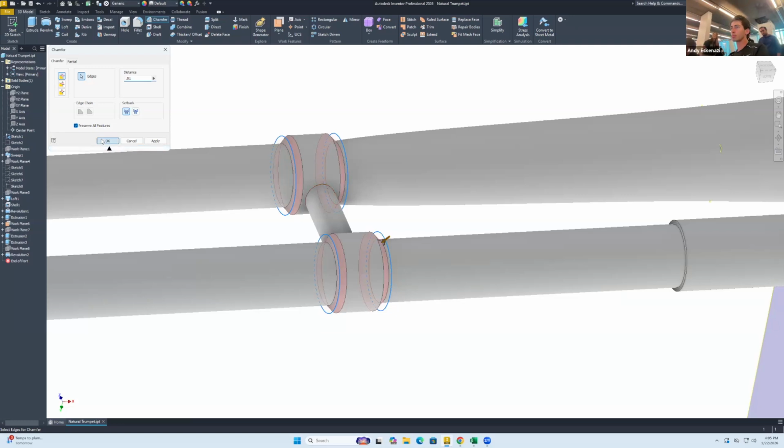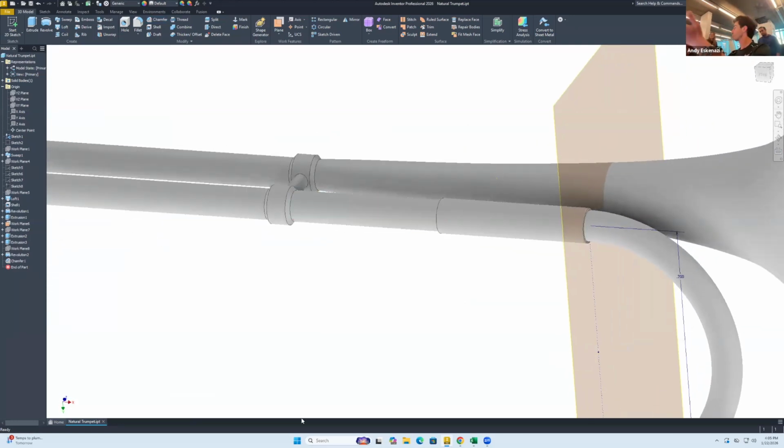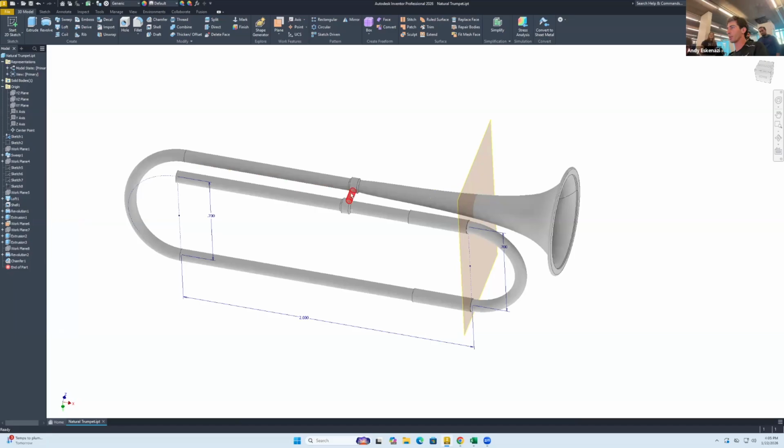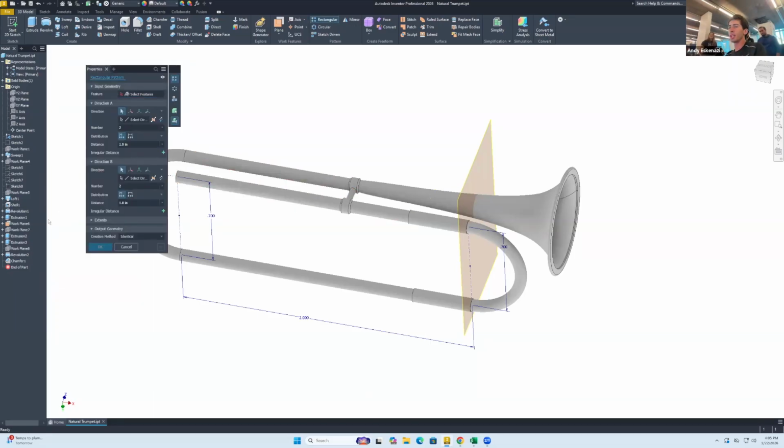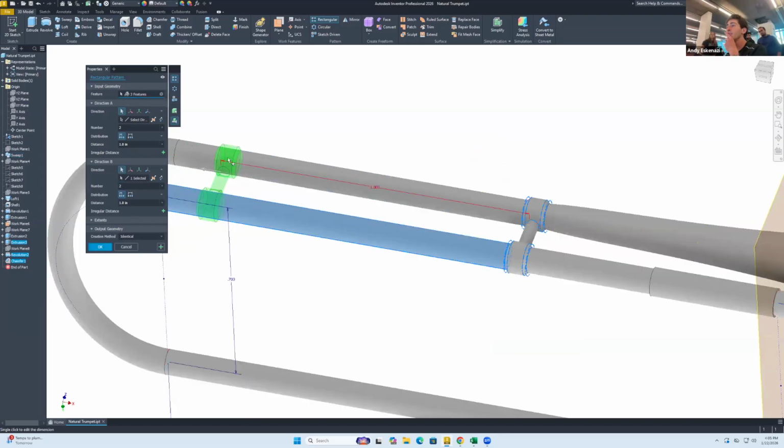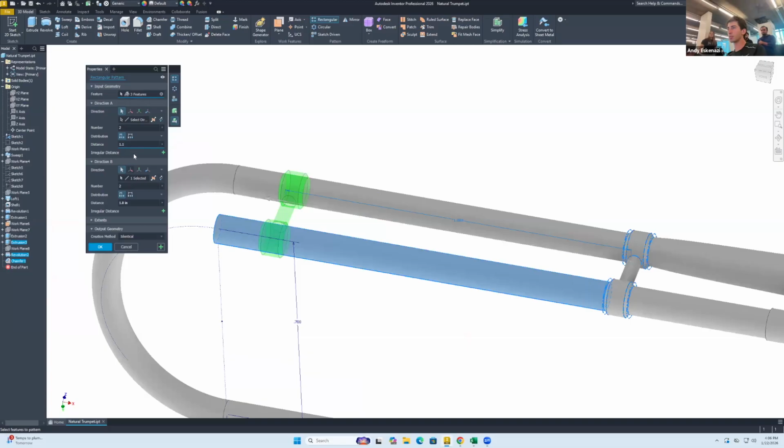Okay. Very easy. Now, what can we do? A rectangular pattern. We don't have to replicate the same work. And we're gonna have that go all the way there too. So rectangular pattern, select features, we'll select extrusion 3, revolution and chamfer 1, then select direction, could be that. And actually 1 inch is pretty decent, maybe let's say 1.1. Let's see if that works.